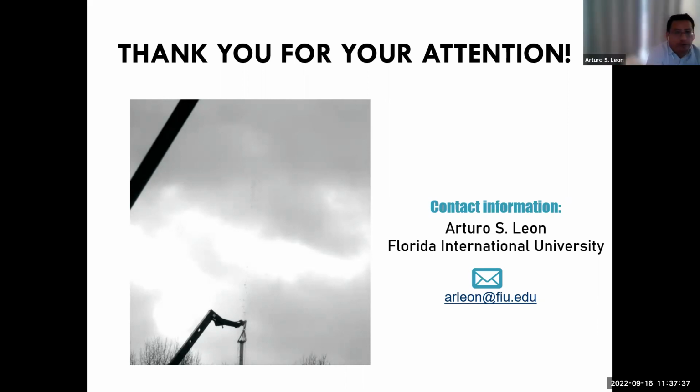Yes. Hi. That's exactly what we are trying to do. We use manholes. Manholes basically are vertical shafts, and the idea is to release the air little by little. If you release the air drastically, like if you have a big shaft and the air is released suddenly, then you are going to have a geyser.